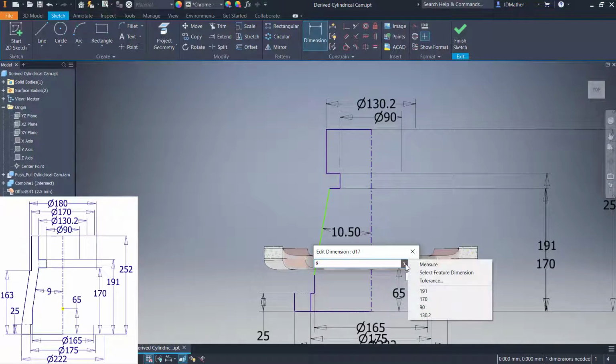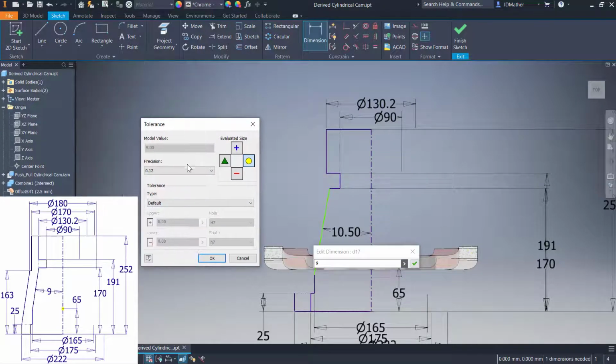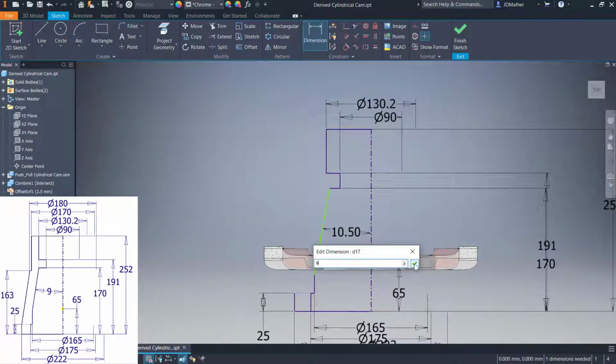Now if you click on the tolerance, you could set that to be 0 decimal places, so there's less clutter on the screen with only the 9 instead of 9.0. And I was expecting that line to turn dark. It didn't, and I see that the height from here down isn't defined yet, but as we define our other geometry, that should fall into place.